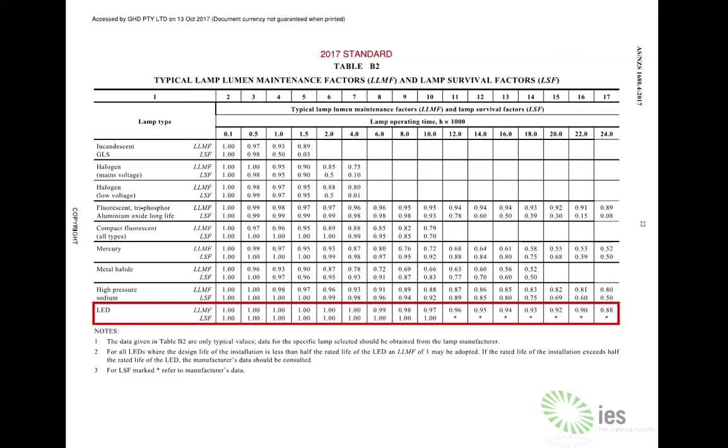Being a DC source, there's no point where you're switching at an uncomfortable angle on the sine wave, but that does happen at drivers, and you might switch at your zero crossing, you might be switching at the top of your peak. That can affect your inrush currents and start tripping circuit breakers. That's one I've heard a lot of recently with LEDs, where switching them on at the top of your sine wave, and as a result, you get your inrush current and your circuit breaker goes ping.